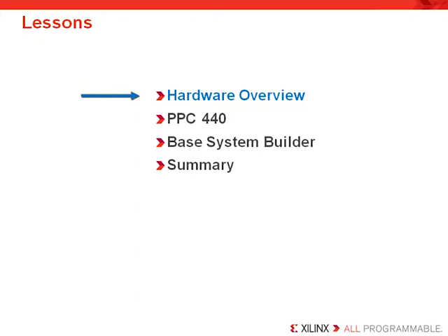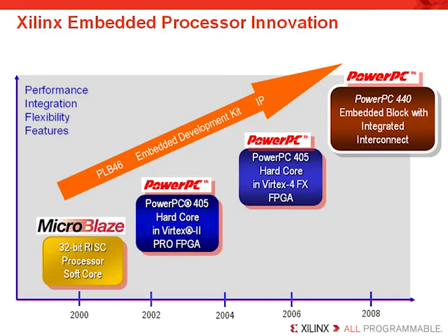So our first topic will be to introduce you to the PowerPC 440 processor and discuss typical embedded hardware. The PowerPC 440 is available from the Xilinx Virtex 5 FX family and is dedicated in the silicon. This means that it can obtain higher performance and have a top speed of over 450 MHz. Now, don't forget that the PowerPC 440 we use is the same as the off-the-shelf version. There has been no optimizing or simplifying of its architecture. It is literally the same ASIC, just fused to the FPGA's interconnect.